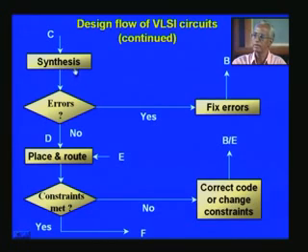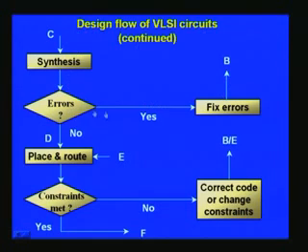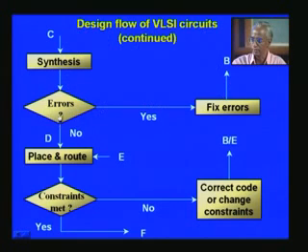So that will be the file that it will create finally, which you can take into the next stage, which is called place and route. And here once again, if there are errors, you have to go back to compiling and do the whole iteration once again till you are totally free of errors and it has allowed you to go to the next step. In this step, since it has created the EDF file, you will invoke the vendor specific platform for place and routing.